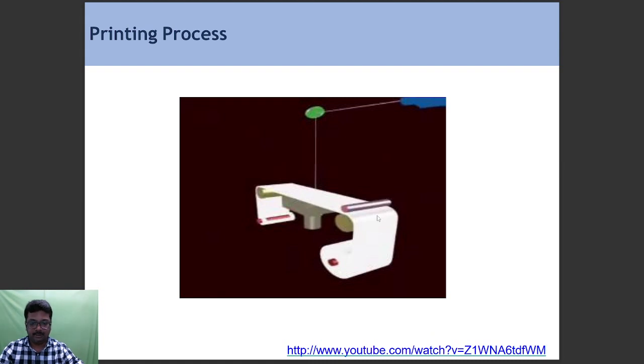This is a roller, and this is another roller which moves in the clockwise direction as a driving force, keeping the material on a flat surface. Then the laser is driven through a mirror and passes over the surface. This area is the mold, where we get the exact output, the part we want. The size of the part is applied here.